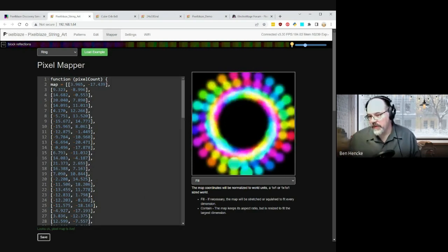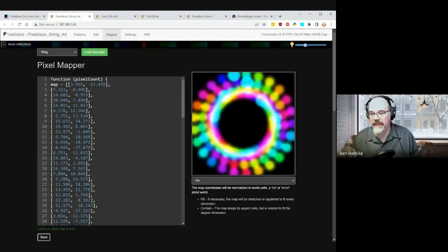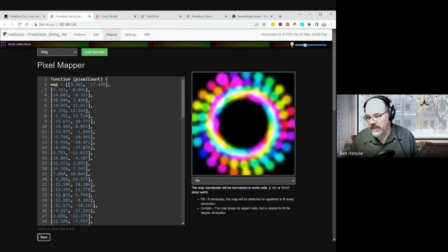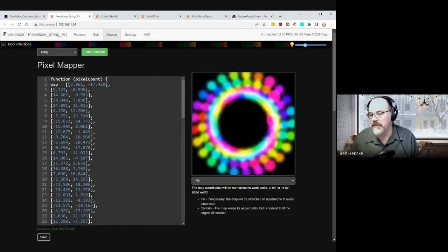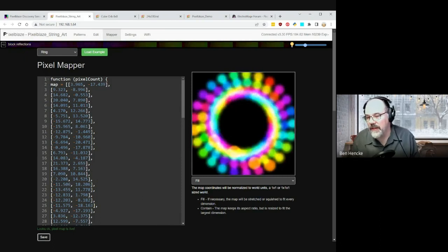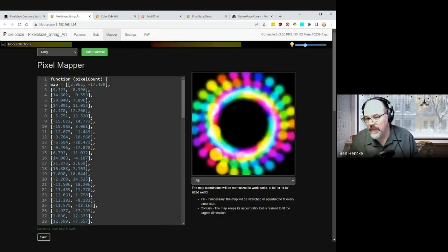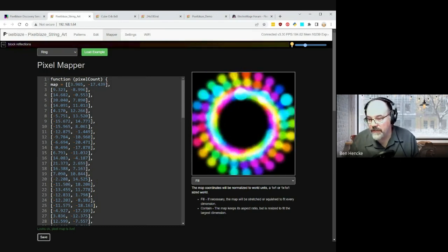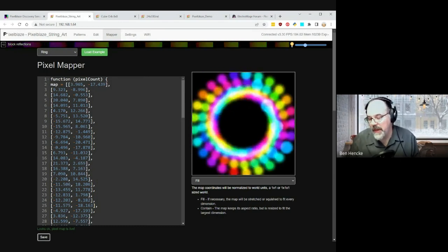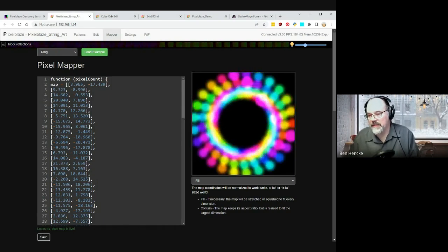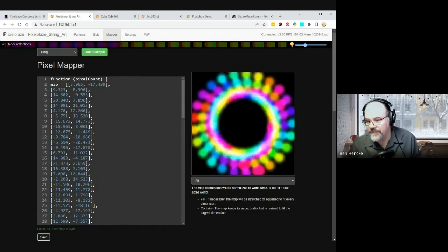And then when it comes time to render out, you just multiply the X value back up to whatever your pixel count is. Of course, for this to really work and keep the pixel to pixel ratio, your pattern has to know how many pixels wide and how many pixels tall your LEDs are. But it still technically could run on something else. So you could run something that's set for an 8x8 matrix on a 16x16. It's just going to double all the pixels up.